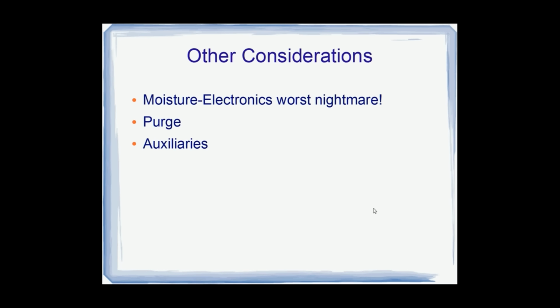And if you have exposed electronic cards or other moisture sensitive devices, you could destroy them unnecessarily because you did not use purge air. Purge air creates a positive pressure inside of the chamber, which prevents moisture from migrating into your chamber. So usually you will always want to use purge air when performing thermal tests.